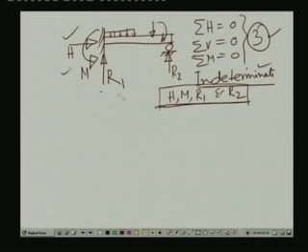Now, for the solution of this, many a time what we do is introduce another condition in a beam. Let us say that we introduce a hinge inside this particular beam, and this hinge is such that it cannot resist any moment, but it can support shear force. It can support the shear force at this particular point, but it cannot resist any moment.